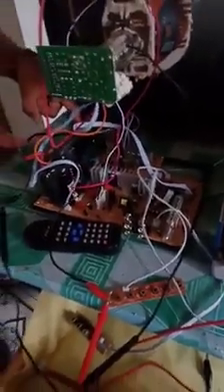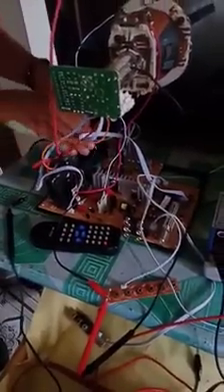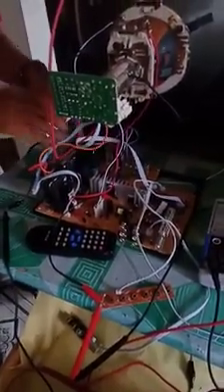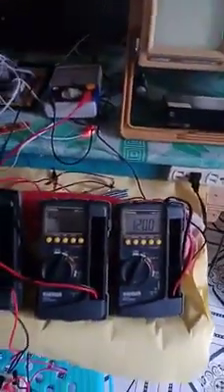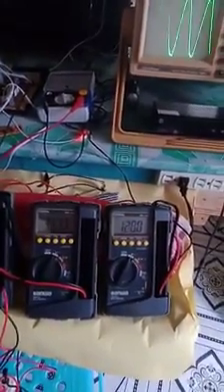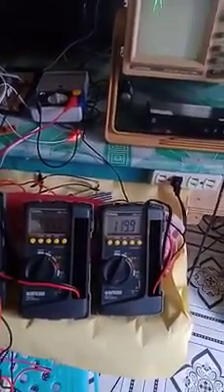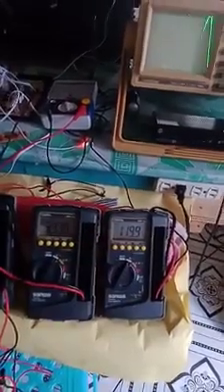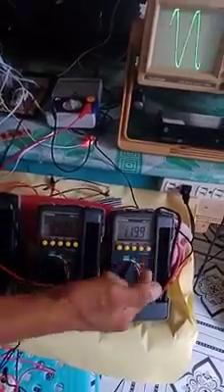Remember that this circuit here is a DC to DC converter, because what is being regulated is actually the DC voltage across this capacitor, which is the input voltage of this switch mode power supply here, the regulator. It is lowered down to 119 volts or 120 volts. So 119.9 volts or 120 volts, that is actually the voltage at the output of the low voltage power supply, which is a regulated one.